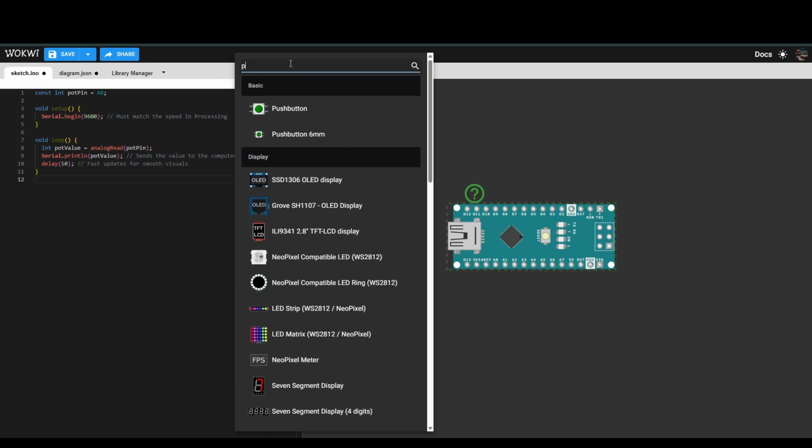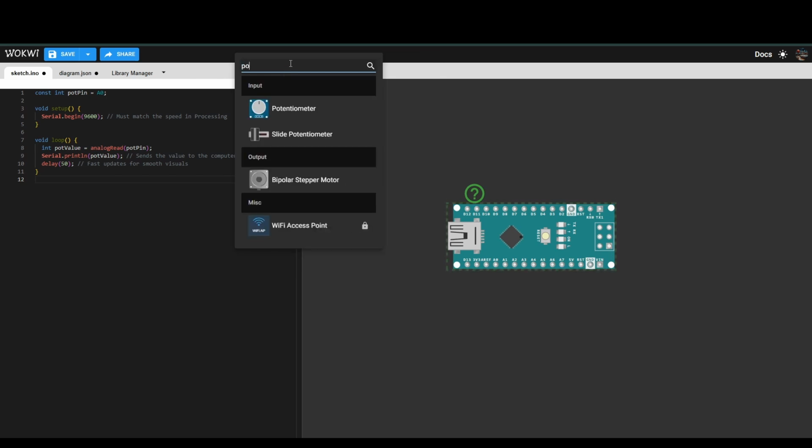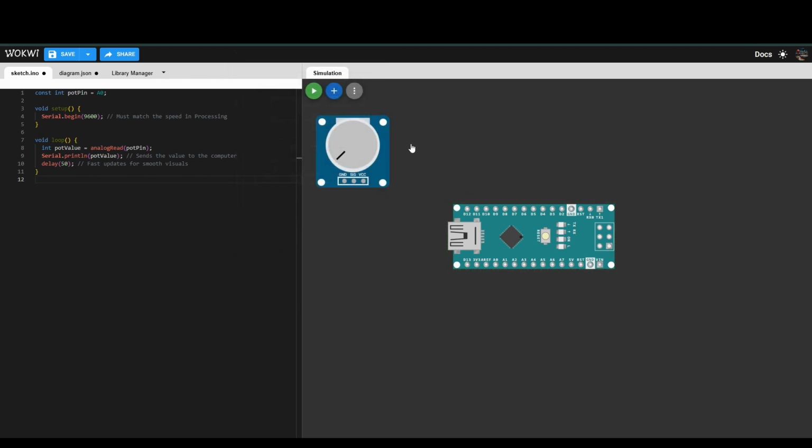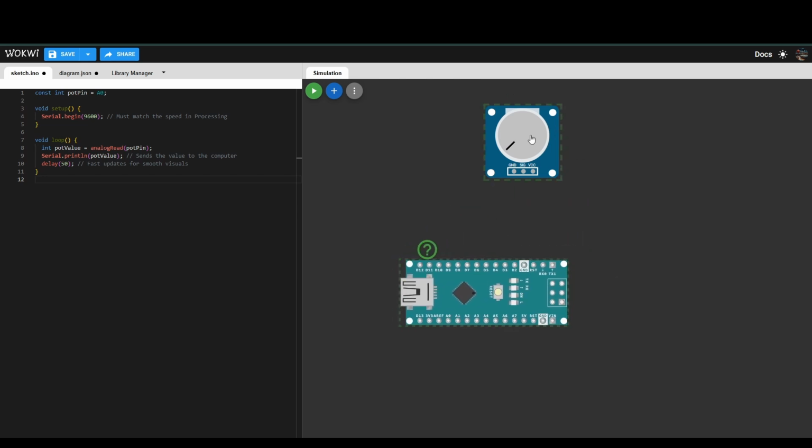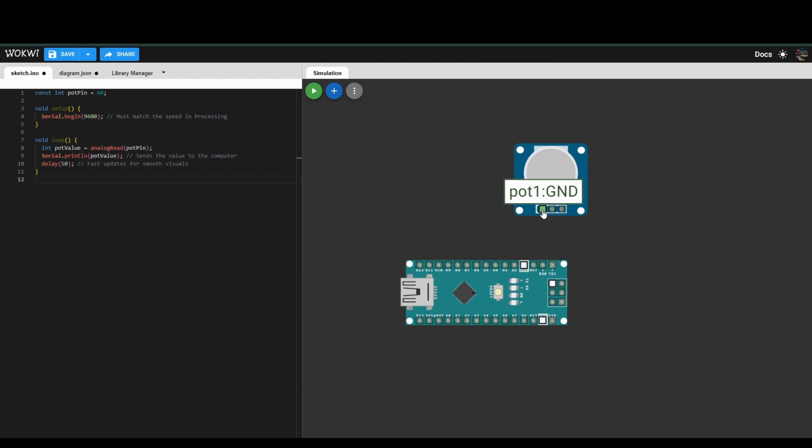It shows how everything is connected: the Arduino Nano, the potentiometer, and the connection of the 3 wires of the potentiometer with the positive, the negative, and the wiper, the signal, which goes to A0, analog 0 of the analog pins of the Arduino Nano.